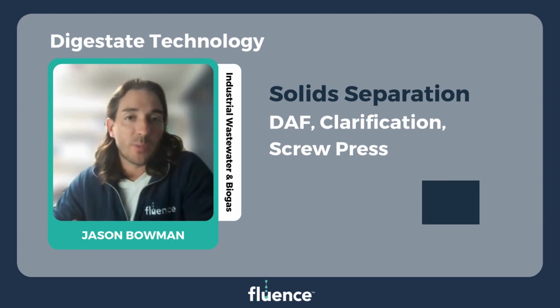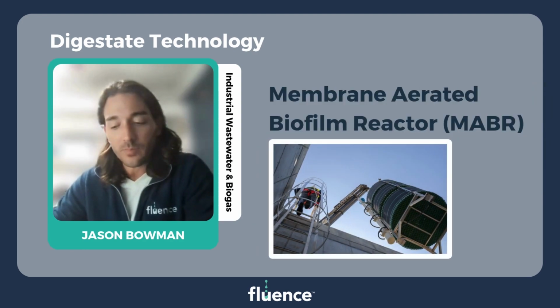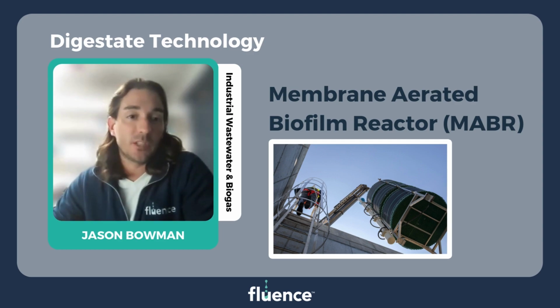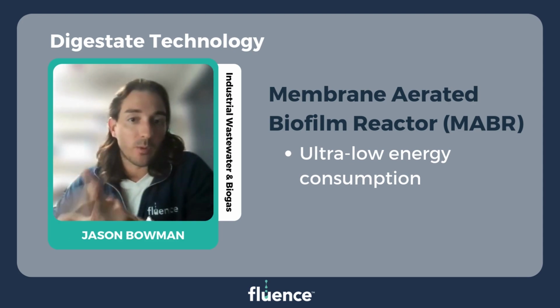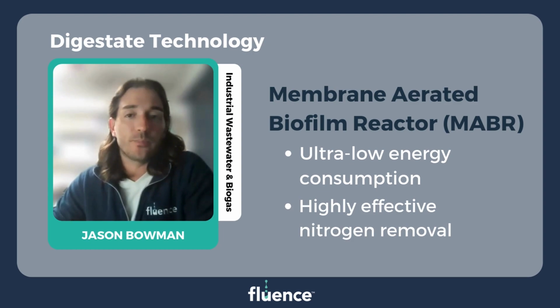So next we have membrane aerated biofilm reactor, or MABR for short. Basically, forget everything you know about membrane-based biological treatment because the MABR process is completely different. This process has ultra-low energy consumption because it's able to combine aerobic and anoxic conditions within the same reactor. We'll talk about that more in a minute. It's highly effective when it comes to nitrogen removal.